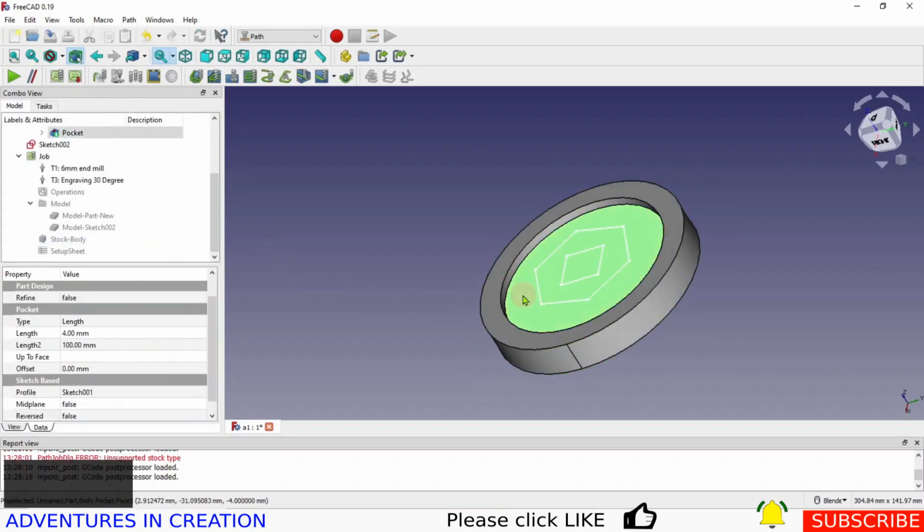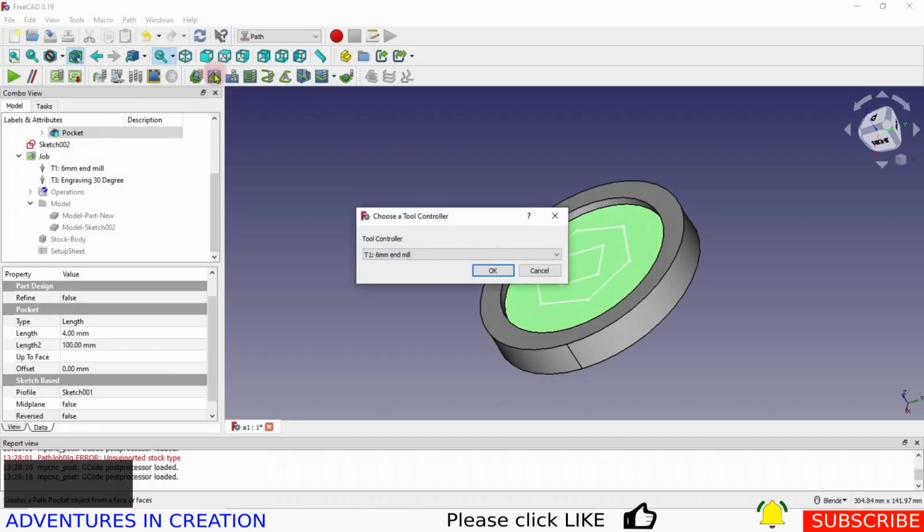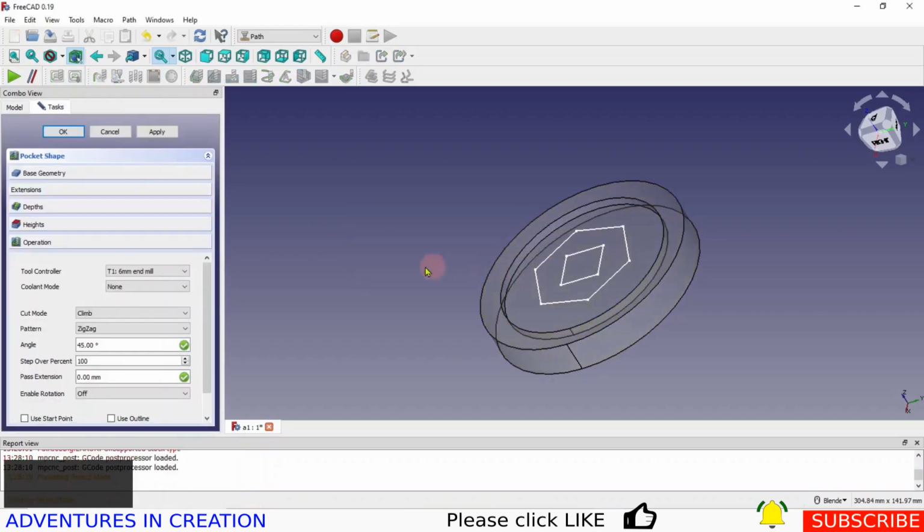And then I'm going to select this bottom surface, and I'm going to say let's create a pocket. And I'm going to use the 6mm end mill to create that pocket, which is a 1/4 inch for those of you who are using inches.